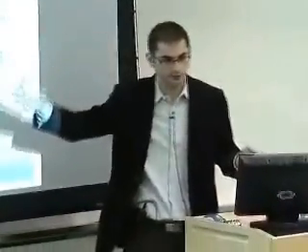When you combine all this together, and this is what I was trying to say in the beginning, it's not about optimizing at the hardware, it's not about optimizing at the application, it's not about optimizing at the MAC or the software. You have to have a cross-layer approach. The purpose of the hardware is to meet the application requirements, and you have to do this at a minimum power overhead. So you have to really do a good job at the hardware level to exploit where the trade-offs are, understand them, and be able to create a very fine-grained power model of your underlying hardware. Now, this fine-grained power model might change according to your software or your application.